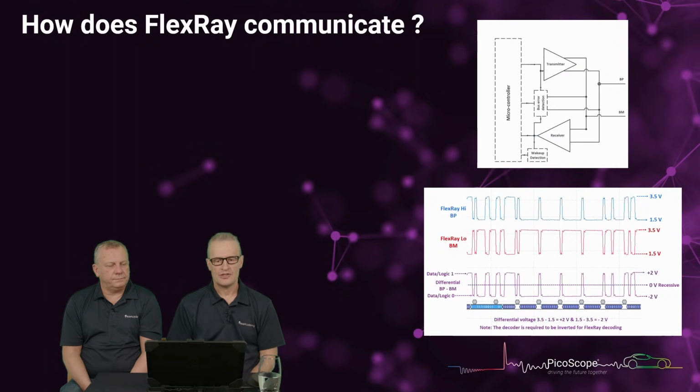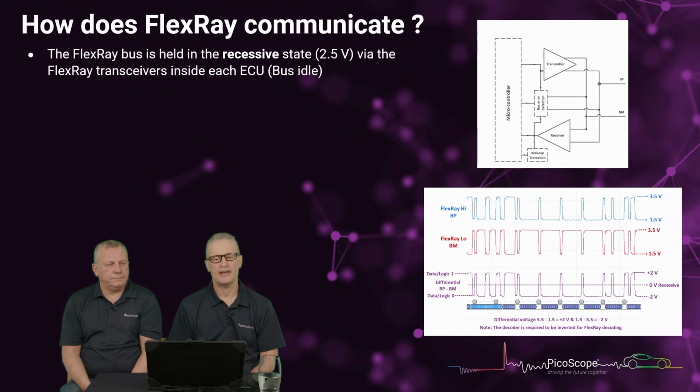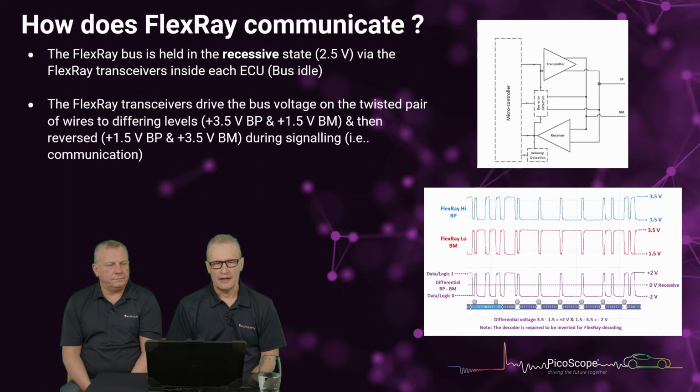So how does FlexRay communicate? The FlexRay bus is held in the recessive state, 2.5 volts, via the FlexRay transceivers inside each ECU. That's the bus idle state. Again, this will sound very familiar.